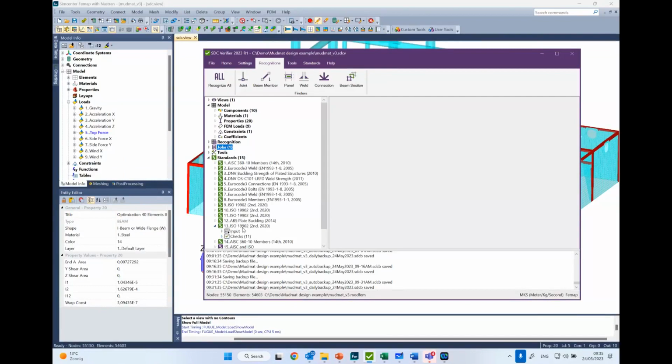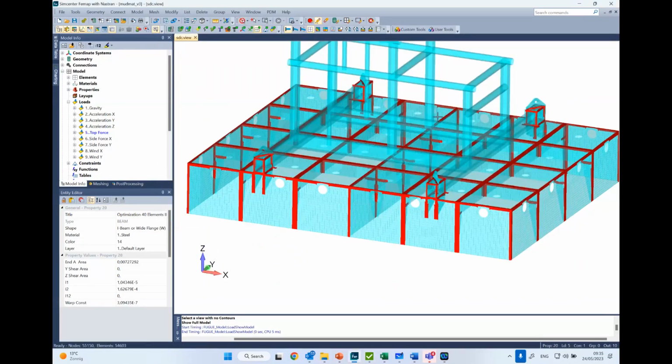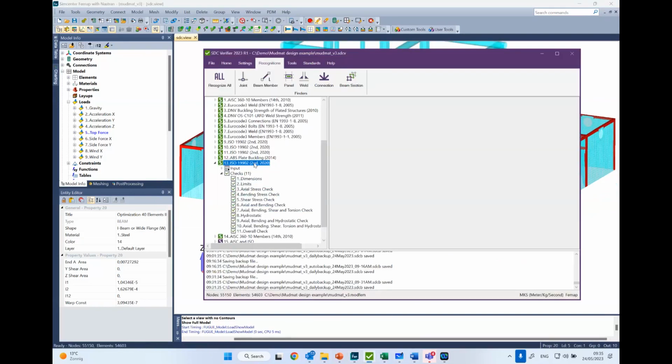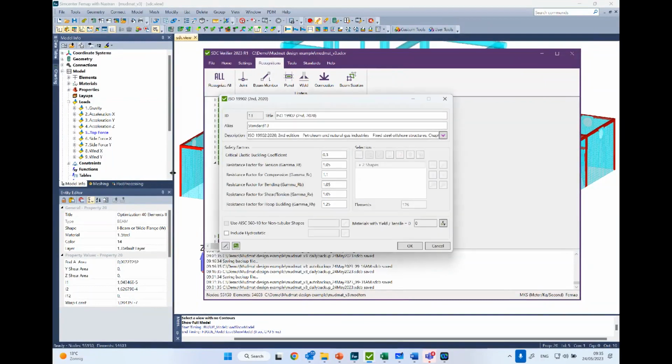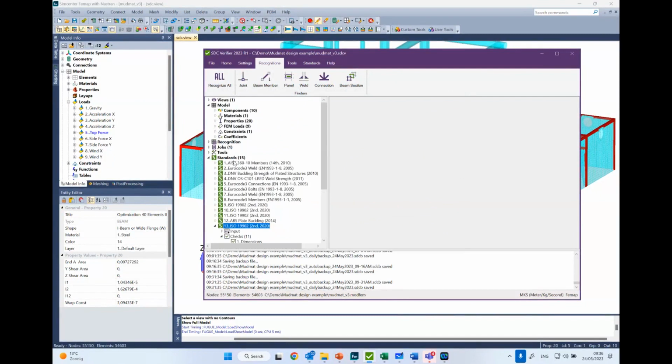For the B members, it is basically a check of axial stresses, bending, and torsion in the B members, but it is only for the tubular members. And in our model, we do have both tubular members and I-beams on top of the mat itself. So we have a very convenient option here in the settings of ISO standard to use AISC check for non-tubular members. When you are creating a new standard, what you do is this way.